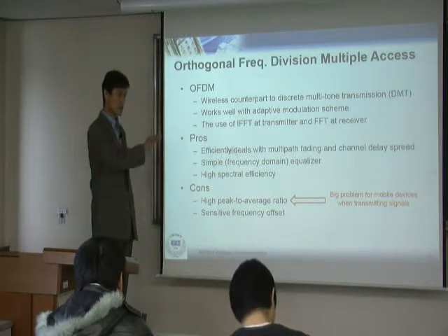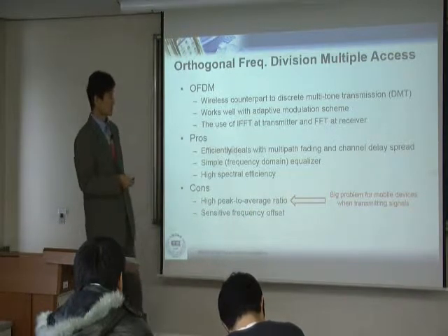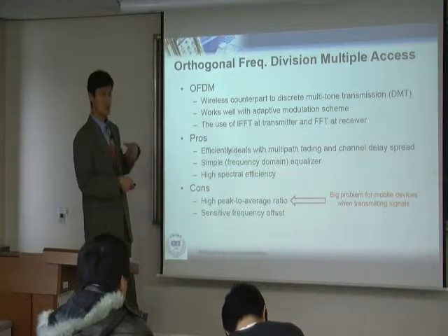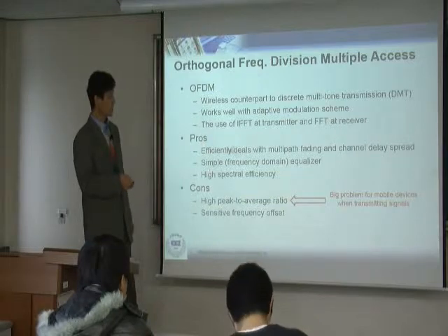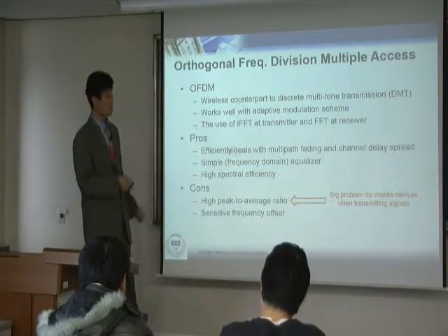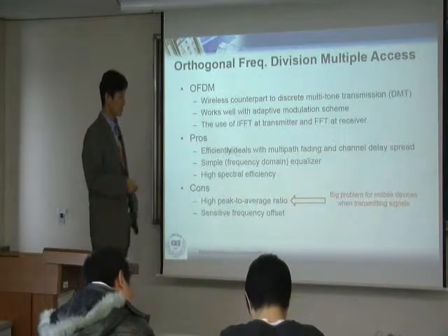So generally you should have feedback. That's somehow an underlying assumption. So the spectrum is more efficiently used. And another thing is that in terms of implementation, OFDM allows you a very simple, just one tap frequency domain equalizer. Okay, this is a very nice thing.